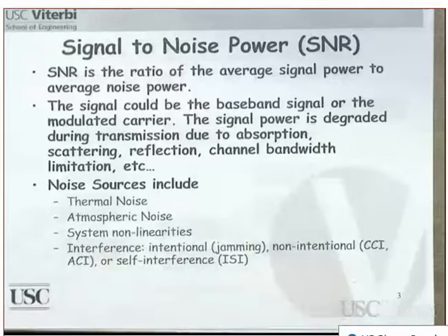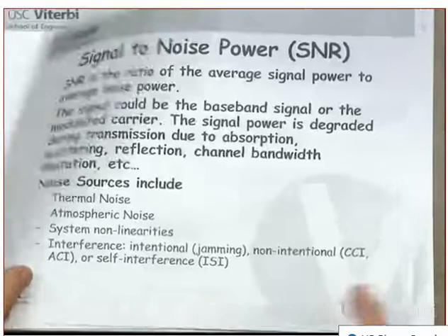Remember, intersymbol interference will happen, and we will see it in detail shortly. It will happen when you transmit at a faster rate on a band limited channel. In other words, the filter bandwidth is less than the rate at which the signal is transmitted. It cannot keep up. Did you get this or not?